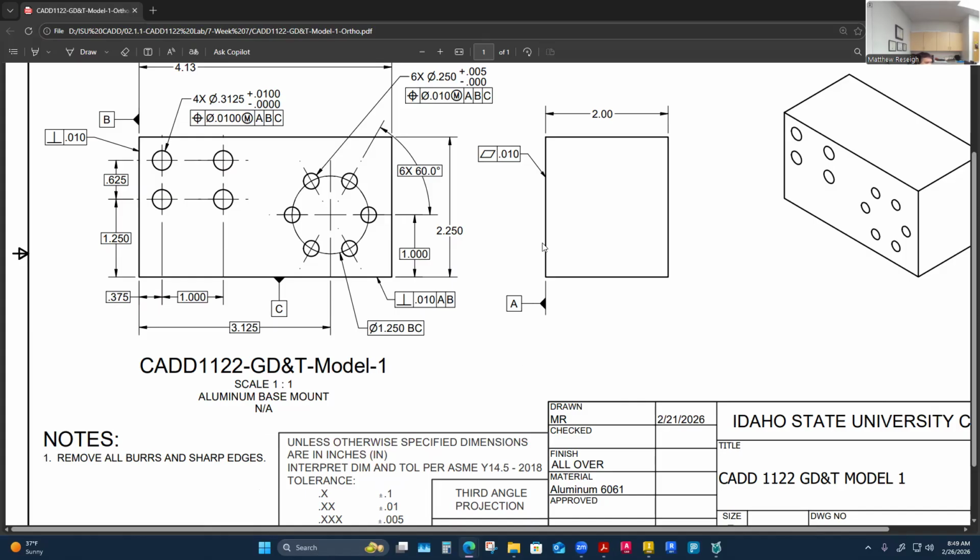And if I look here, it looks like front side surface is datum A, and it has a flatness control at 10 thousandths. So right now this is totally fine in how to establish them. You'll see that Inventor will bundle them together, which is also okay. I could have bundled these together as a drafter, pointed to this and then hooked my datum to here. That just means I'm controlling datum A as the front surface with a 10 thousandths flatness, regardless of feature size.